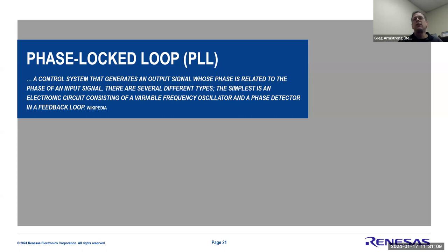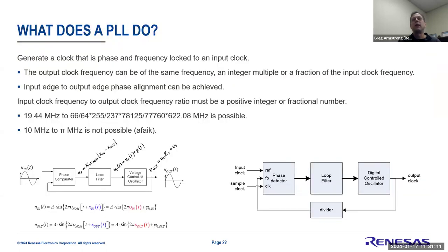So all a phase lock loop is doing is much the same thing. But it's now just using a clock as the input, right? So a clock, as we highlighted, has events that are occurring. That's the rising edge, and they occur at a very statistical interval. It could be a 25 megahertz clock, a 156.25 megahertz clock. Any type of clock is coming in, and what you're doing is trying to measure the phase relationship of that clock back to a feedback mechanism, so of your output.